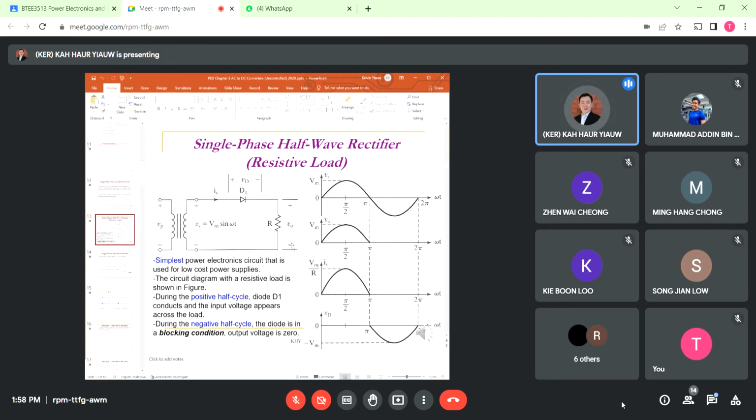This one, for circuit analysis, you also study. If the circuit is open, when you measure this point and this point, you should ignore this resistor, right? Because you are measuring an incomplete circuit, so you measure 0 value. That's why there is no value here. The same thing applies to your current. The current is actually blocked by the diode D1 here, so there will be no current.